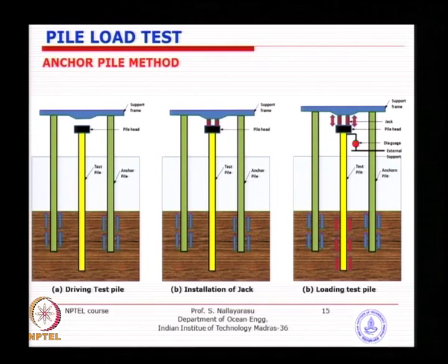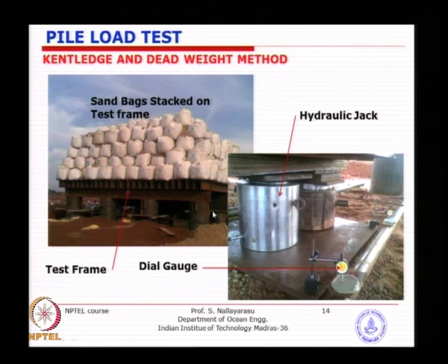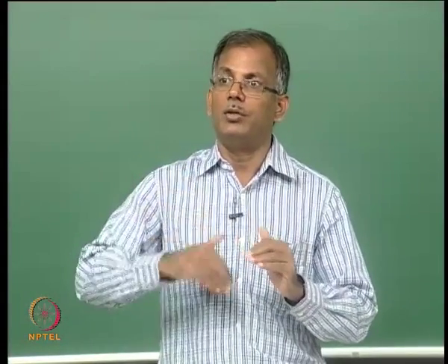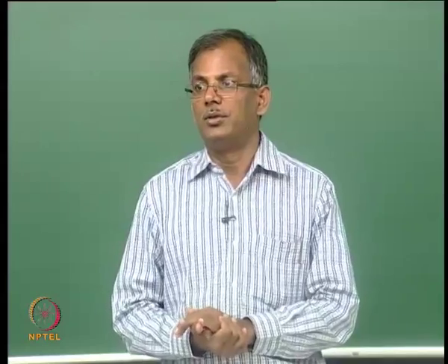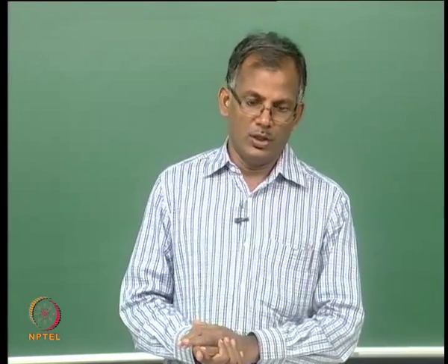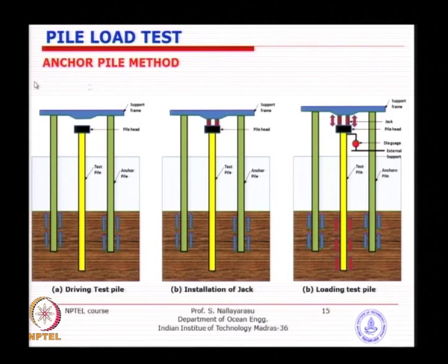So, that is where this method becomes a little bit difficult, because it might become very expensive, and when you compare with this, maybe this is better, because you do not need to mobilize so much material movement every time, because it is not one time. You will see later that these sandbags have gone back and forth several times, because you have to do a loading sequence and unloading sequence, and you have to repeat the test at least 2 times, and that is where you find it is a time consuming process and also very expensive.